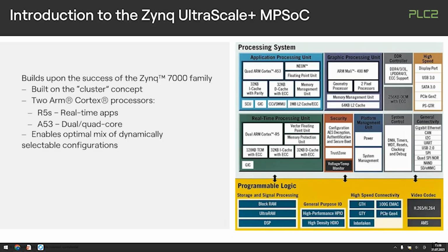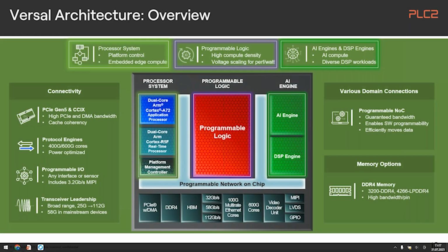When we look into these setups, you can also see the challenge: you will have to program the CPUs in a proper way in order to use whatever the programmable logic offers. And there's structured design support from Vitis and the tool flows that basically allows the CPUs to well understand what is there in your setup that you have created, and you have a register-based flow between the two sides for control flow, in order to set up things or know about the state of the operation inside your mission mode logic. So that's the core idea of the system design with these devices.